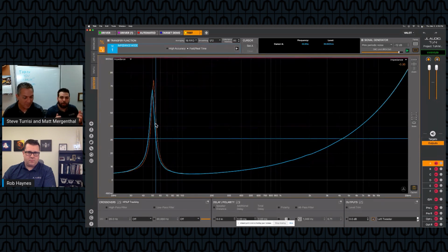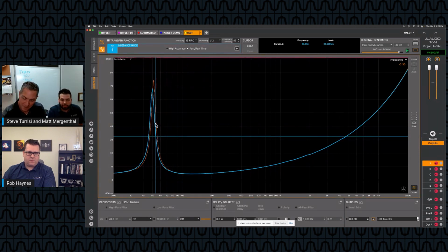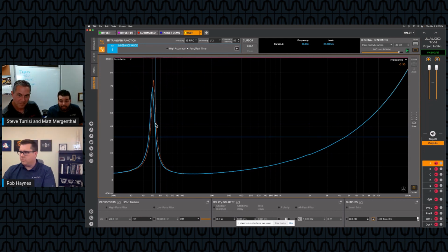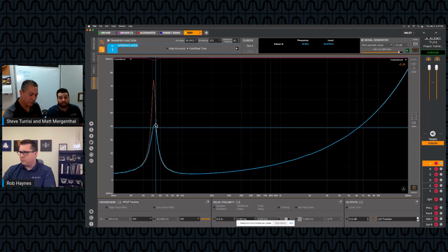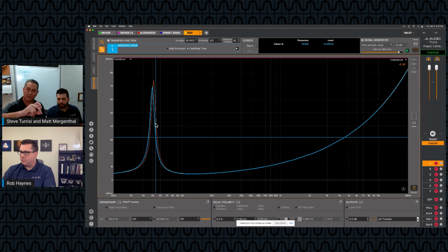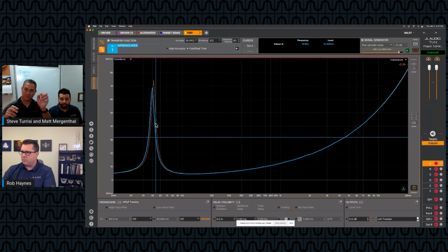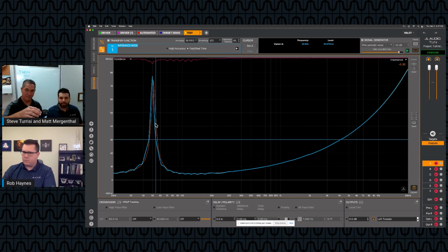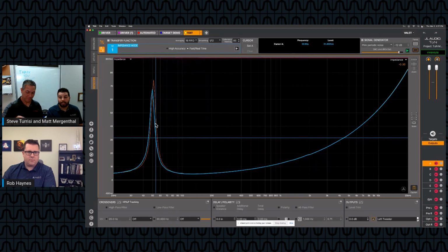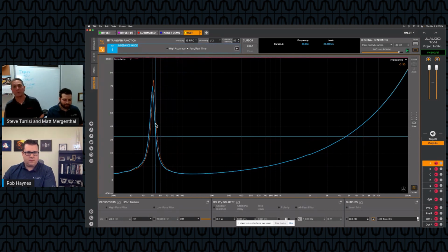You might think, well, it's barely pushing on it. What's it really going to do to the speaker? You see that just a tiny little thing. I'm looking for something, a little clippy thing here. All I did was I dropped a little twisty tie on it, and it made that kind of a change. Ready? I'll do it again. Yeah, that's a big deal. And it's nothing. It's just a tiny little thing. In other words, impedance measurements are very detailed, very accurate, and can give you a really good indication if something's affecting the motion of a speaker as it's moving.